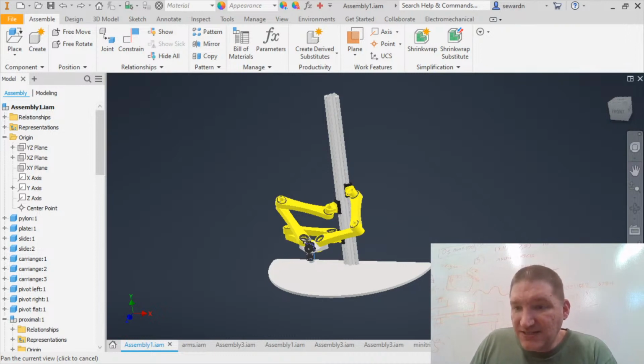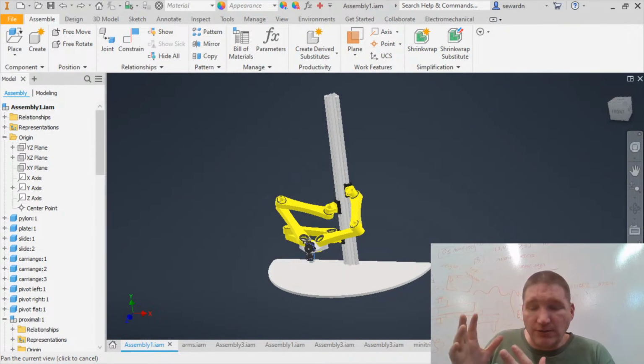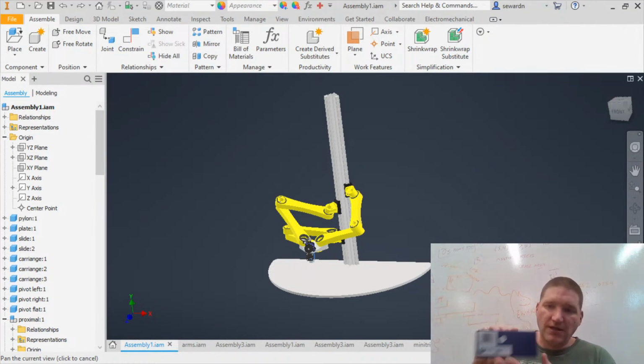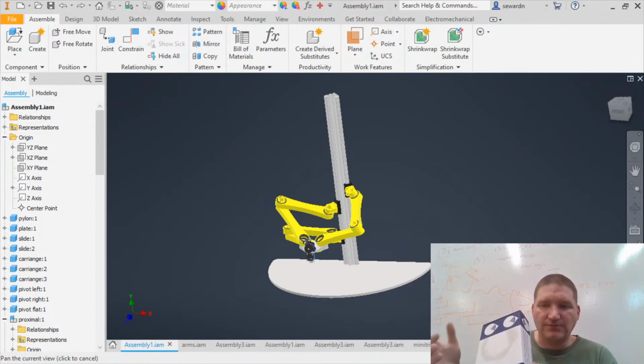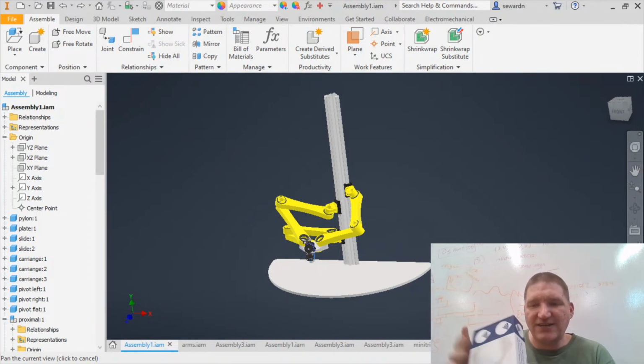All right, are there plans for the machine? Let's see, Radish Dalek: are there plans for the machine to have positional feedback? I imagine a single magnetic strip shared by each sensor, 1 sensor per carriage. Yeah, feedback would be great. I'm going to use this controller here, and it will actually know if it misses steps, so I can know if I ever lose position. I'll just tell it where to go, and the steppers will go there. If it ever can't handle it, it'll miss, and then I can take action. So any kind of feedback on the carriages won't really give me any more than what I already have.